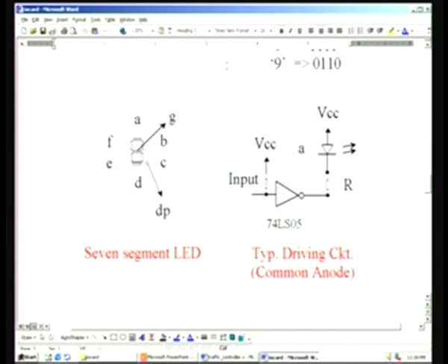There are 48 of them, and each is once again pulled high by a pull-up resistor, and when it is not connected, a 1 will be pumped in here because this is an open collector output, and thereby it can sink current, and the LED is connected in this fashion. The 7 segment LED we are going to use on the board is common anode type.